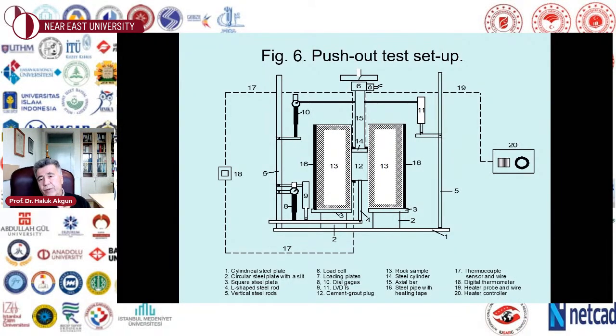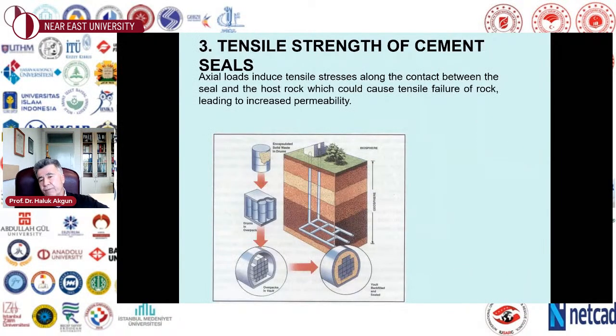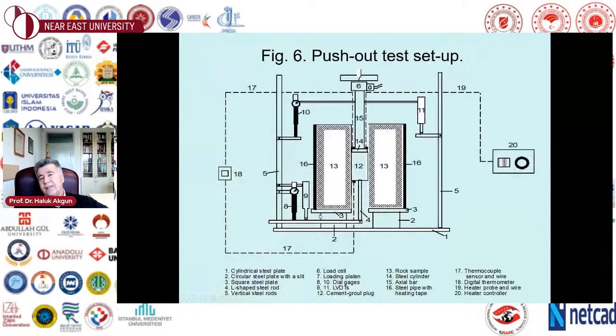We wanted to test this scenario of a borehole or shaft within the rock, that we use for access to deposit the waste, the nuclear waste. So what we did is we had a core of rock. There was a cylindrical core. We put a coaxial hole in it. We plugged it with cement, self-stress 2 cement that was provided by Dowell Schlumberger at that time. And we wanted to simulate the condition of this water column, axial load. What is the effect of that on the cement plug that we have?